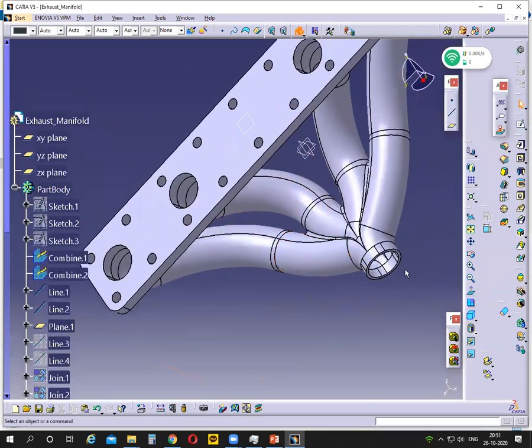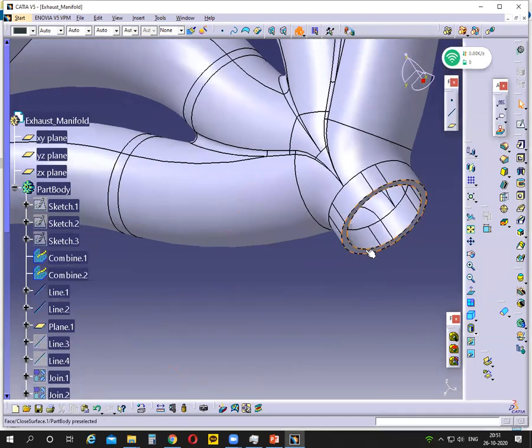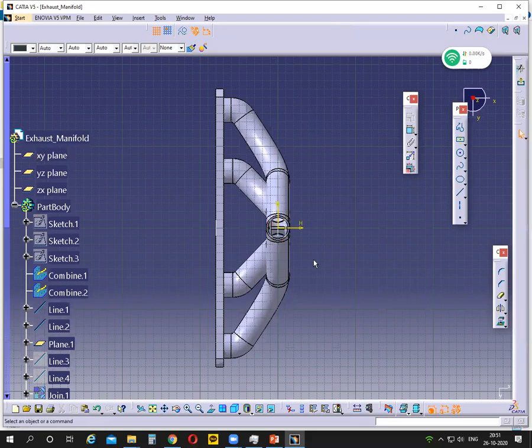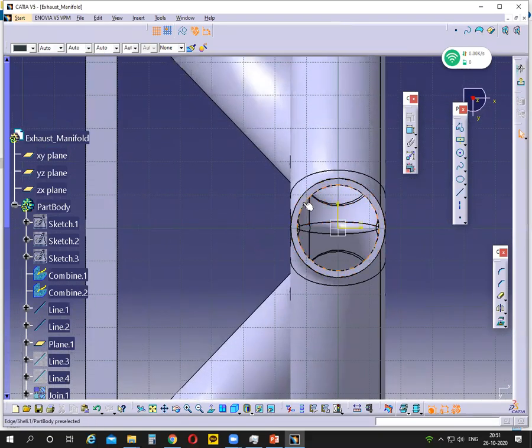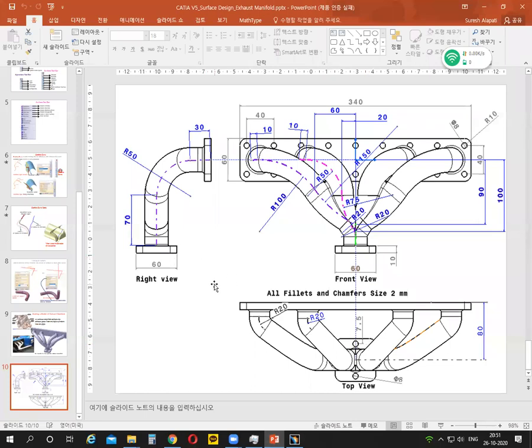And similarly at the bottom, so we can make the sketch there. So which plane? So select this plane, or you can create a new plane. But we already have a plane, right? Once we have a surface means we have a plane. So this is a plane. And same, 60 millimeter, 60 millimeter. So 60 millimeter and 10 millimeter is pad thickness, and we have 4 holes. Actually, here only showing 2 holes. We have 4 holes here and here.